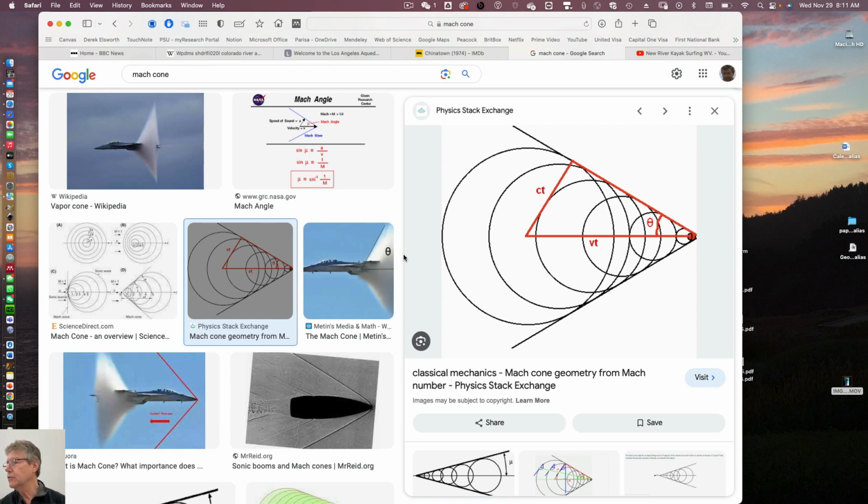So the reason that commercial planes fly at 600 miles an hour, not 800 miles an hour, is that 800 miles an hour is above the speed of sound. And so you have to use a lot of energy to fly at that higher rate, and you also have to build a sturdier plane. The reason is that if you think about the rate at which sound waves can emanate from the tip of this plane, they can only travel as fast as they'll be carried by the speed of sound in air. If you're flying faster than the speed of sound in air, that energy given by that wave and the sonic boom can't get away from that.